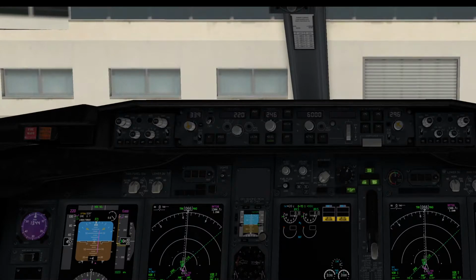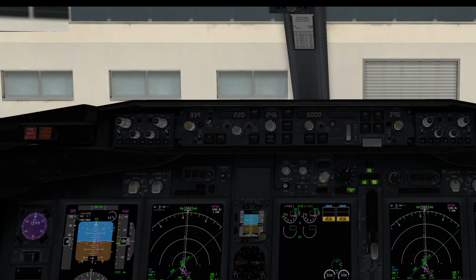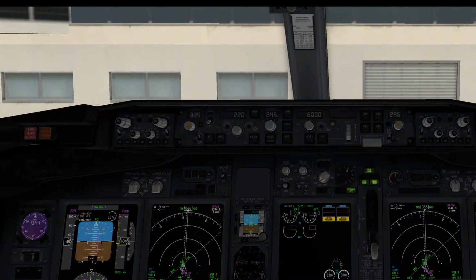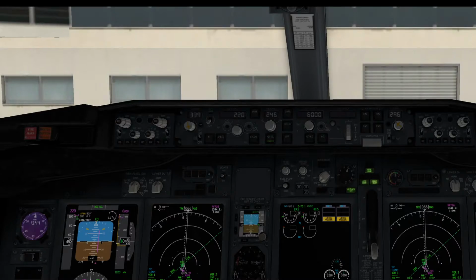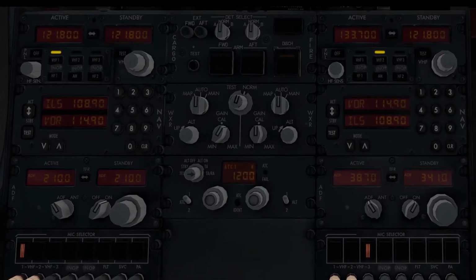So altimeter is set 1023, auto brakes rejected takeoff, flaps 5 set. Tow connected and bypass pin inserted. Release parking brake. Parking brakes released. Now, starting pushback, and you may start engines.